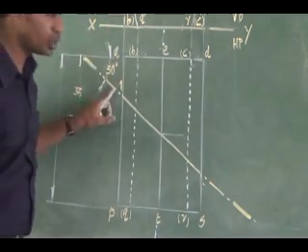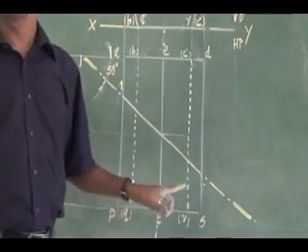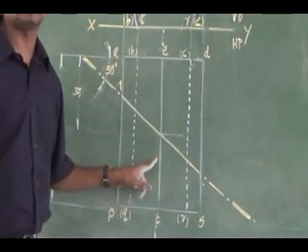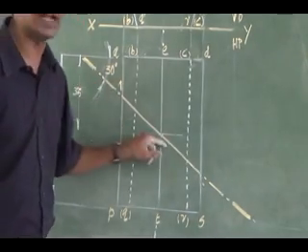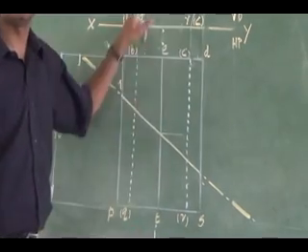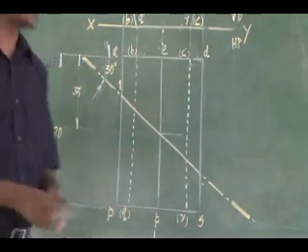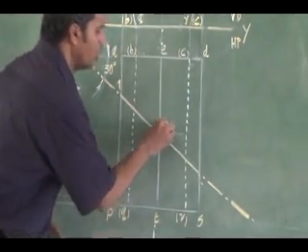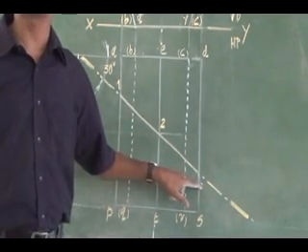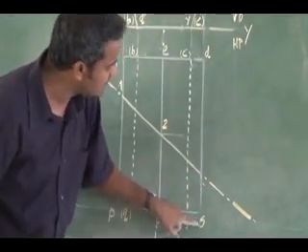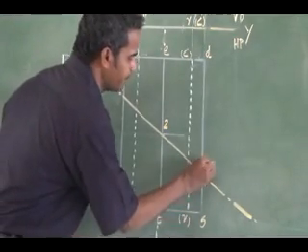PA, right? Then you go along the cutting plane looking for the visible cutting point first of all. What is the next visible cutting side edge I have? Next visible side edge along the cutting plane is TE. TE is my visible side edge. So there I will get my visible cutting point 2. Right. Then you go along the cutting plane looking for the visible cutting point and visible cutting edge. So the visible cutting edge is SD. So there I will have my cutting point 3.